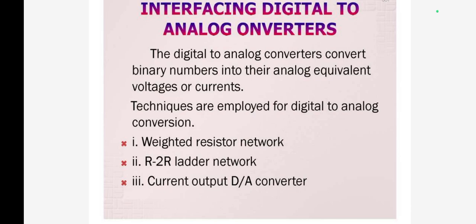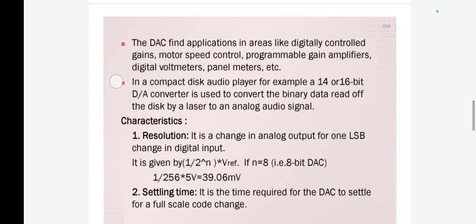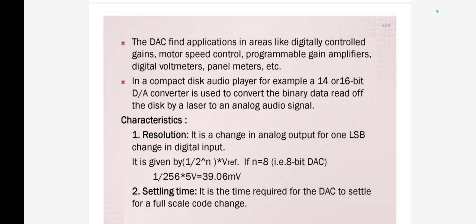This IC1408 is an 8-bit R-2R ladder type DA converter compatible with TTL and CMOS logic. It is designed for use where the output current is a linear product of an 8-bit digital word. The techniques employed for DAC are the weighted resistor network or R-2R ladder network current output DA converter. The DAC application areas include motor speed control, etc.